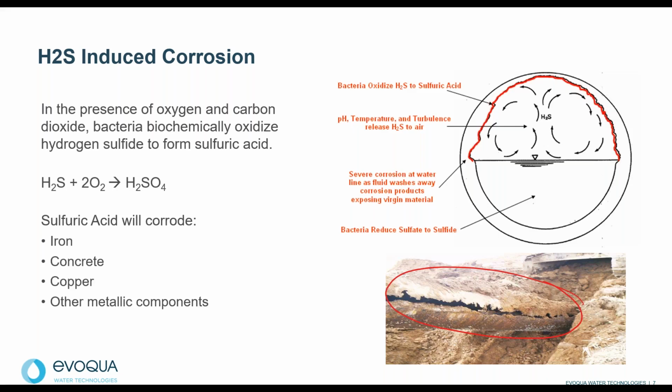damage. In sewer collection systems, corrosion damage is very commonly observed in iron force mains or concrete structures such as gravity sewers or wet wells. We also see corrosion in copper electrical wiring found inside control panels located at lift stations or wastewater treatment plants. Corrosion can also occur at wastewater treatment plants with other metallic components such as structural members of the plant, gratings and walkways, or even large pieces of equipment such as grit collectors, bar screens, and sludge press conveyor belts.